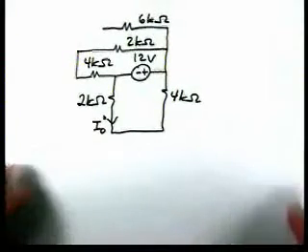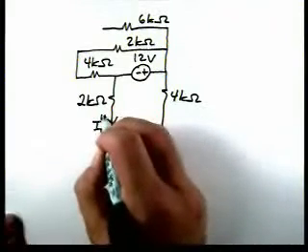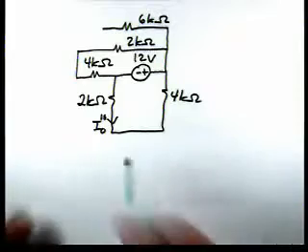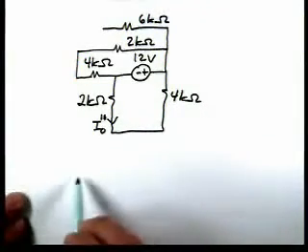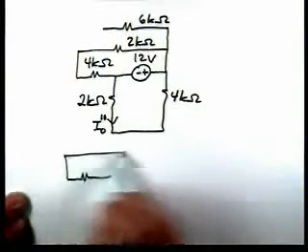So now let's continue and find the contribution from the voltage source. So here's I0 double prime. Now, these two resistors are really in series. Let's redraw this circuit and combine those resistors.